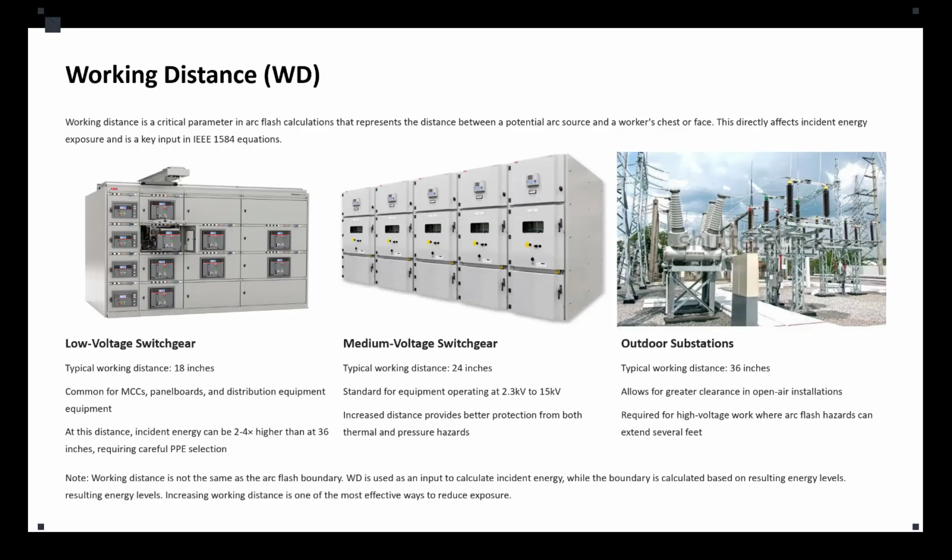Now, let's talk about the working distance. We mentioned that it is different from arc flash boundary. This is one of the most influential inputs in IEEE 1584, and it is often misunderstood or applied inconsistently with this standard.